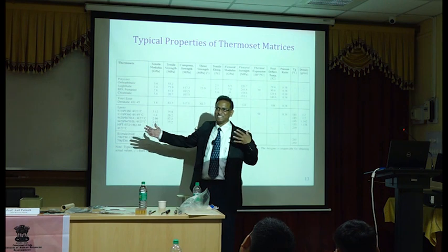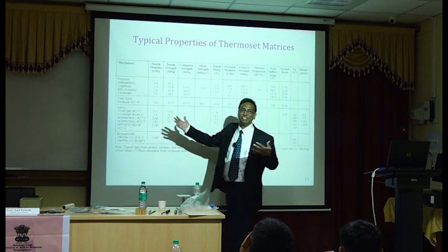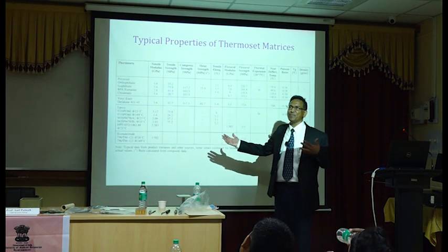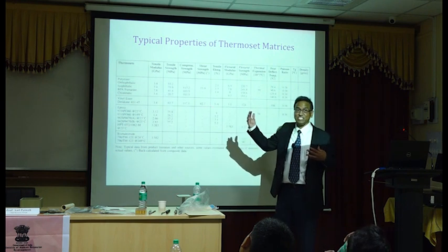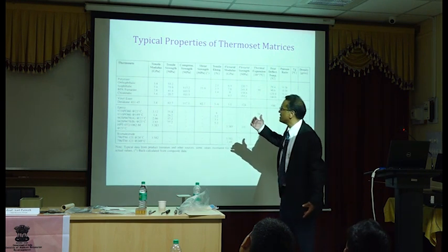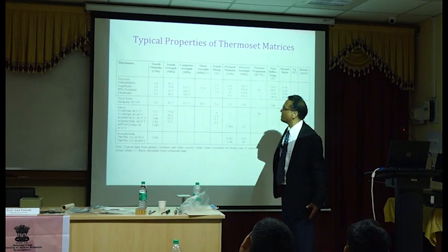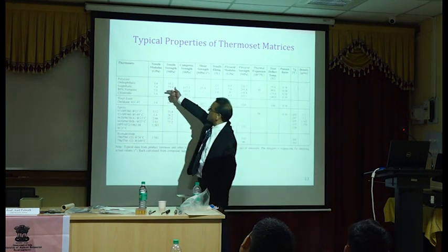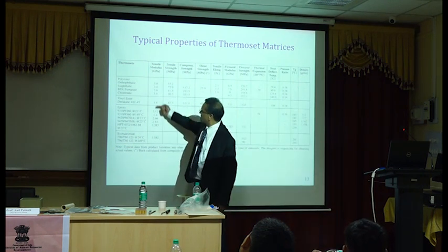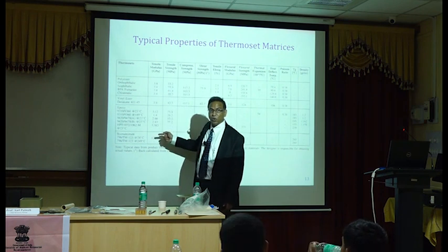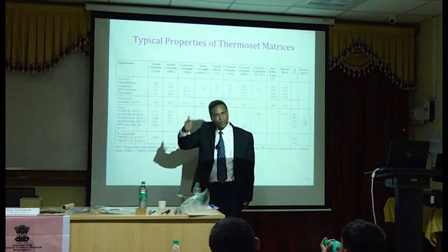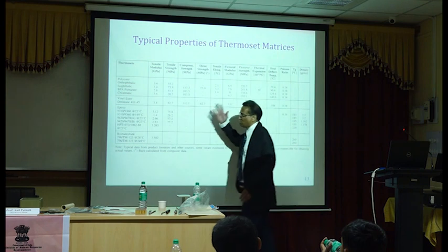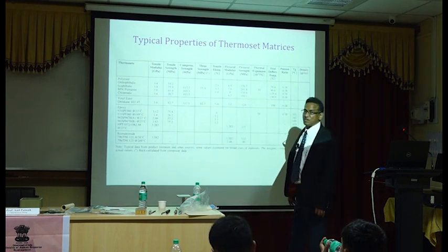Can you see the difference? It's a huge difference, right? Steel is a very stiff material, very strong and also stiff material. Whereas matrix, not so stiff. The modulus is very, very low. That's what you might be able to remember. Oh yeah, matrix very, very weak in terms of modulus.